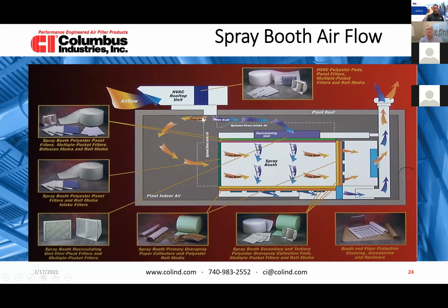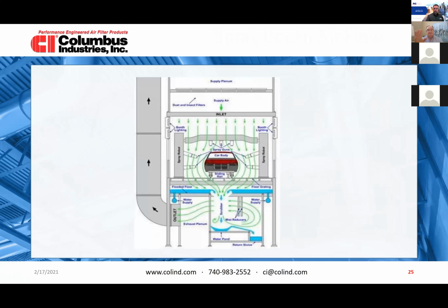The cross draft, again, brings in the air, it goes across, and then across the filter bank, which is here, and then a final maybe filter, and then up. So the fan would be at this level, basically pulling the air up this way. So those are the 2 drafts, flows in the spray booth.